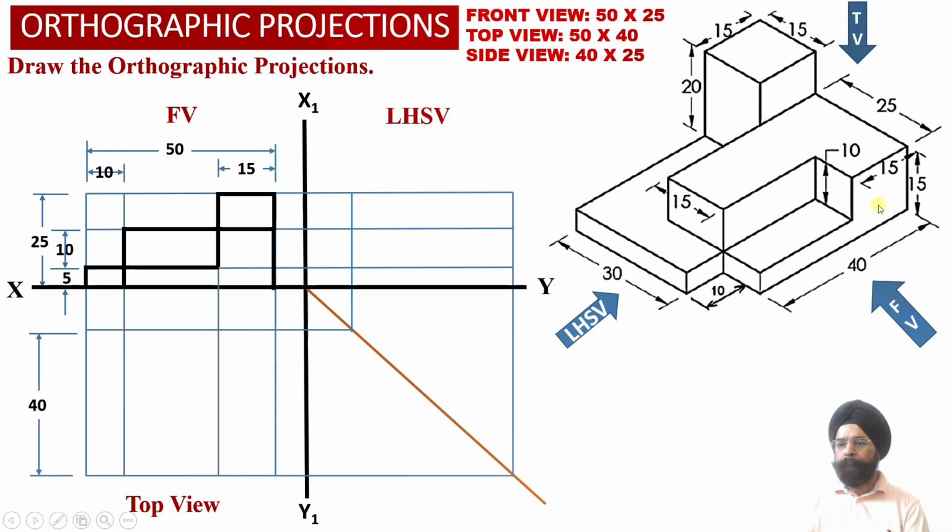So we are going to obtain a hidden line projection into the front view projections corresponding to the base of the square prism, which is lying on top of element number 1 over here. This way we have been able to obtain the front view orthographic projections of the solid.